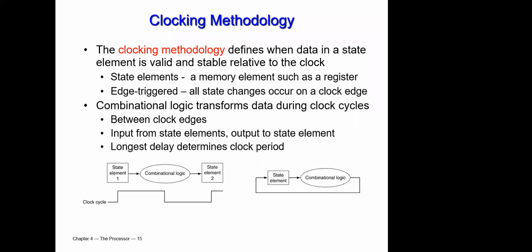So we have previously shown that we basically have sequential or combinational logic. If you have any clocking methodology, this basically means that we will need sequential logic. You can have a particular state, let's say state 1, which will go to state 2 at each positive edge of the clock, so you are changing the state. However, in between, you can have combinational logic that will do a certain particular task. And we will see that, of course, when we begin to implement the mini CPU in Verilog. You will do something like that, exactly the same concept.